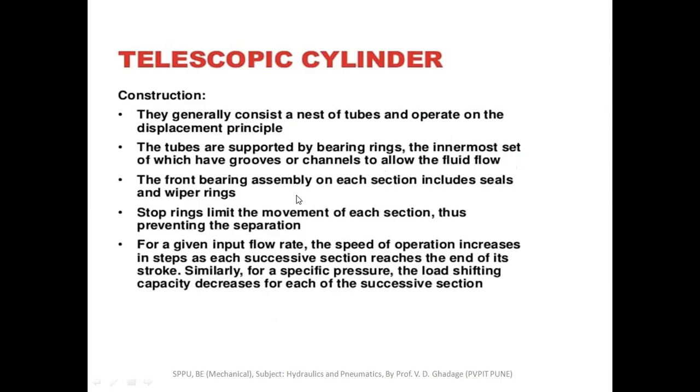The front bearing assembly on each section includes seals and wiper rings. Stop rings limit the movement of each section, thus preventing separation. For a given input flow rate, the speed of operation increases in steps as each successive section reaches the end of its stroke. Similarly, for a specific pressure, the rod lifting capacity decreases for each of the successive sections.